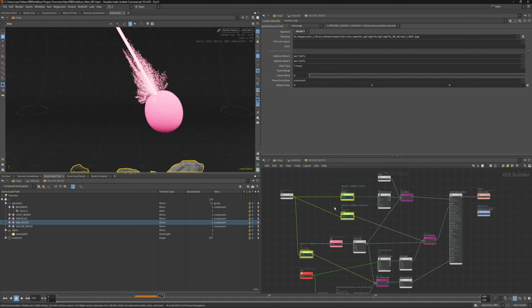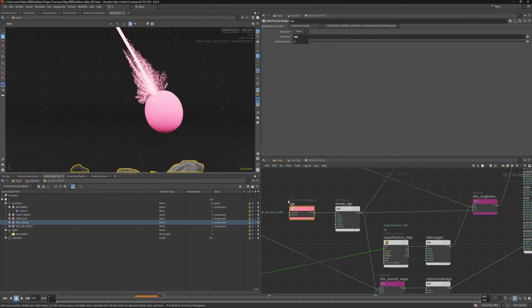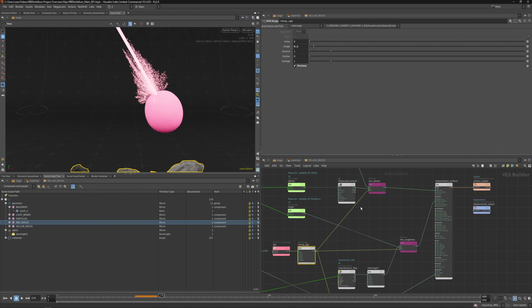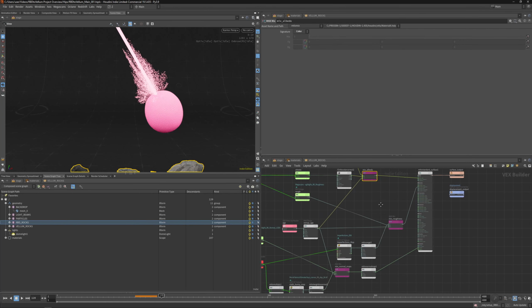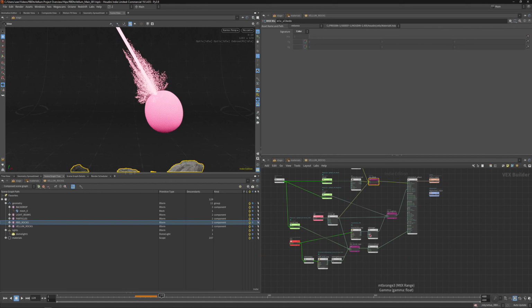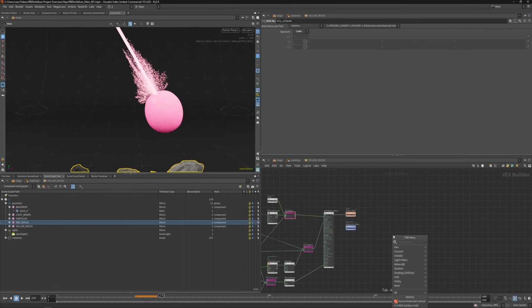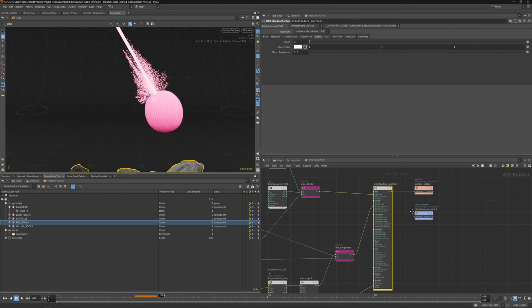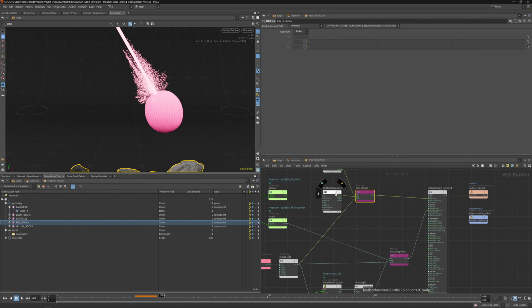The green ones actually is the rock materials. And what I'm doing is I'm using this age attribute. This is like a primvar reader, so float age attribute. I'm remapping this age attribute, and then I'm using this to blend each channel. So why I'm doing this like that is because with the Karma XPU, you don't have ability to blend between the BSDF surface materials. So you can't really blend those materials with the XPU. So that's why I'm blending each channel.